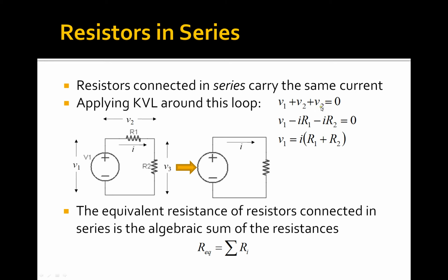Now I'm going to use Ohm's law. Remember that V is equal to IR, and the voltage supply is fixed. We can replace V2 and what should be V3 right here with the current through resistor 1 and the current through resistor 2. Remember that those values are the same. I is the same through each resistive element, and we multiply that by the resistance of those two elements.